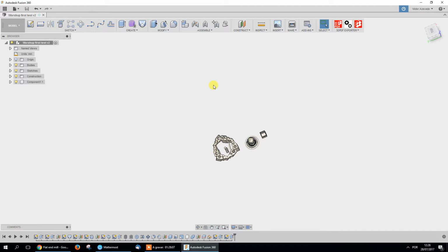Also, there's other features like when you want to change your sketch to other plane, you can do it. You just have to redefine sketch plane. So sometimes when you change or make a cut, your plane vanishes and it says a warning, you have to redefine your sketch.